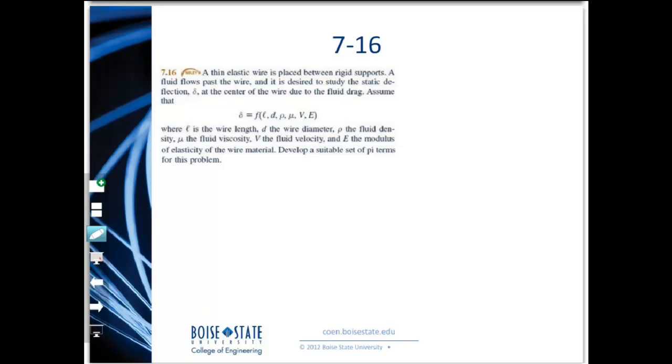So let's look at a problem where we try to apply the Buckingham theorem, at least for the first few problems. A thin elastic wire is placed between rigid supports. A fluid flows past the wire and it is desired to study the static deflection delta at the center of the wire due to the fluid drag.